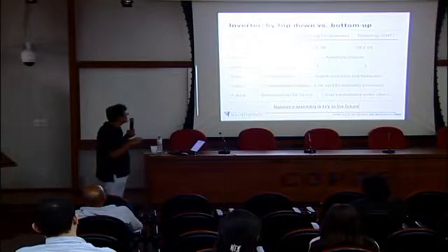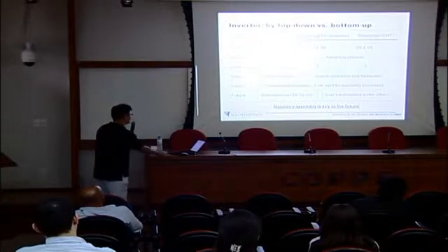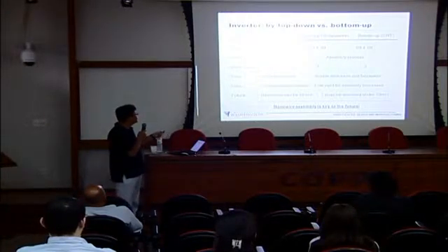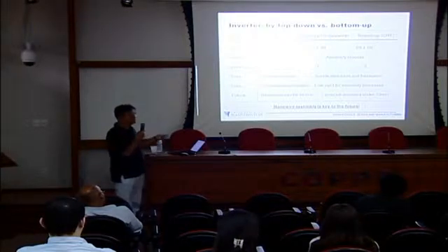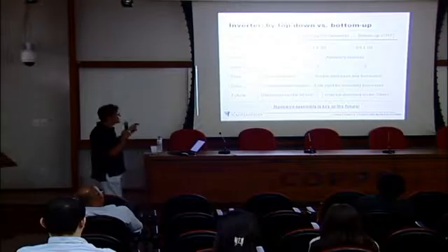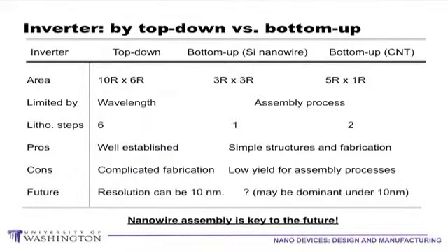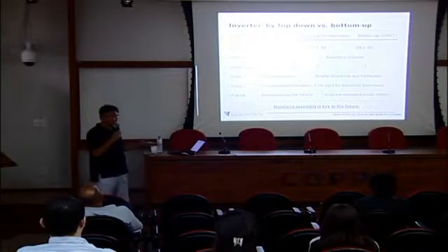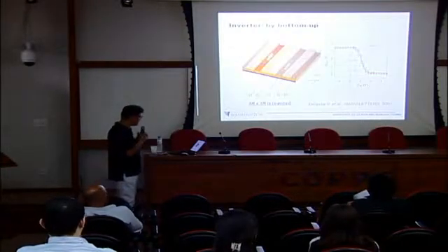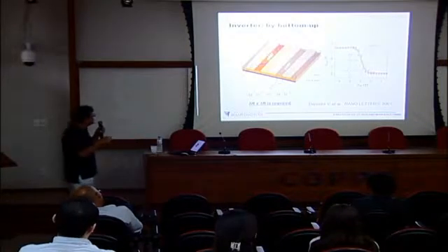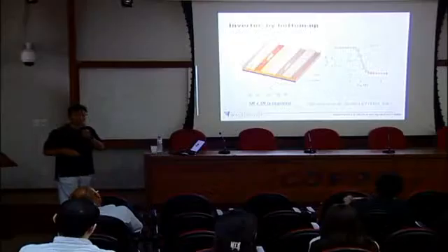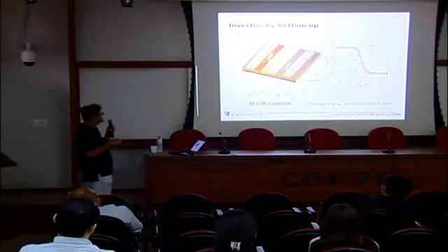The limitation for the top-down method now has several factors, but in semiconductors, I would say the wavelengths are limited. Okay, so that's why we can fabricate only up to 20 nanometer or 30 nanometer at this moment. And for this method, silicon nanowires or nanotubes should be assembled very precisely. Okay? If you see this AFM image, the orientation of this gap is not perpendicular to this nanowire. Okay? We need to think about how it was fabricated.